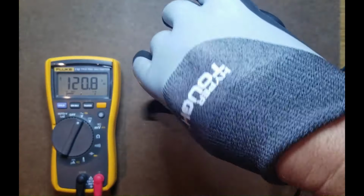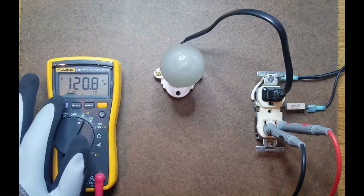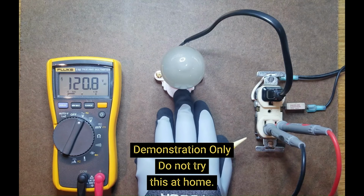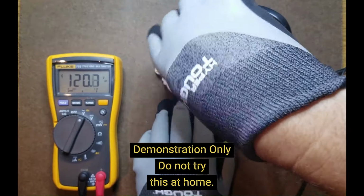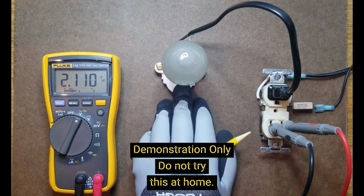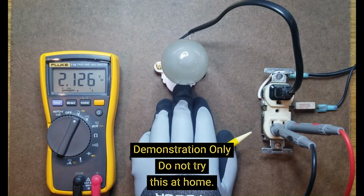What happens if I screw this light bulb in? We're still reading in traditional volt reading mode. If I screw this light bulb in, look what happens to the voltage at the outlet. Voltage has dropped down to 2 volts. You see the problem here.